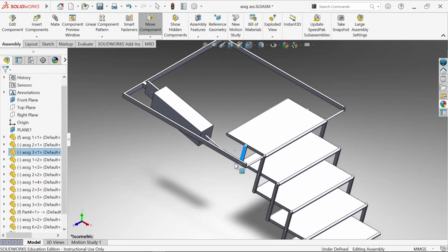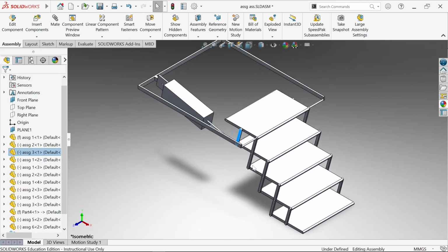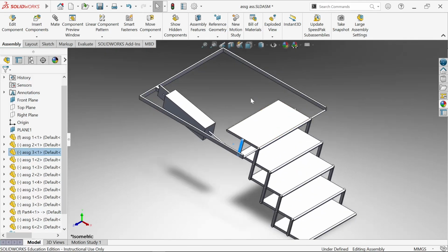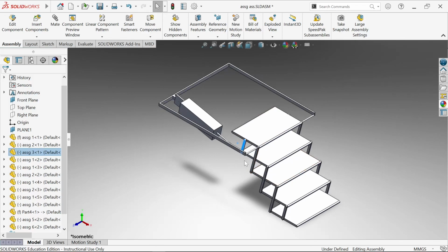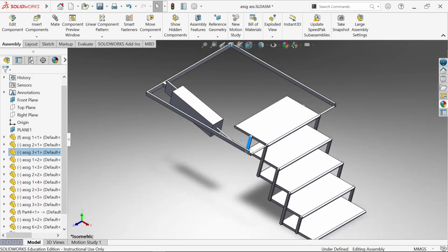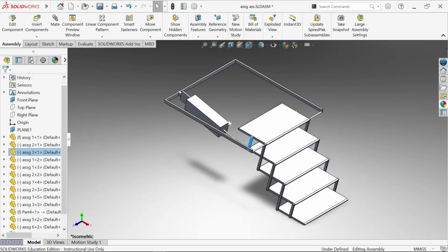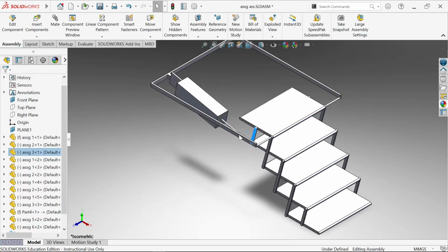Now let's understand the mechanism of it. As previously mentioned by Arunava, this is a double rocker mechanism. That is, we have two rockers, and they are basically in a non-Grashof chain, because they have two dead center positions, and we are not rotating any link completely. Basically, we are not cranking any link.